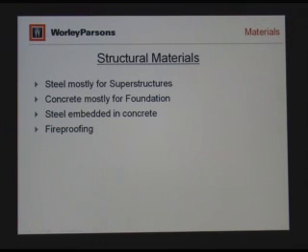For foundation work, we use, of course, reinforced concrete, although for some structures and even for some pipe racks, we have used reinforced concrete. The choice is really if a pipe rack, for example, needs to be fireproofed. In some cases, it's found to be more cost-effective to use reinforced concrete columns and beams as opposed to using steel and then fireproofing it. But again, the majority of use for reinforced concrete is for foundations.